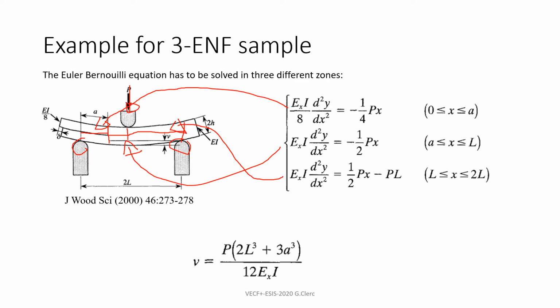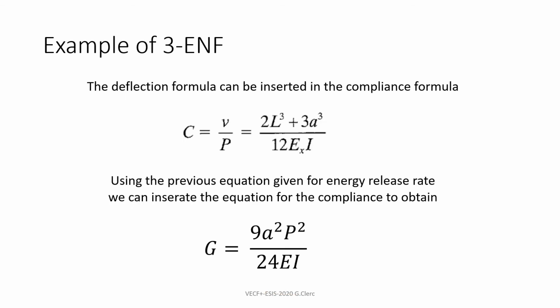If you want to see the detail, you can check this publication from Yoshida, where the solving is described in more detail. But here, due to short time, I will simply give you the solution. That's the deflection here in the middle of the beam. Then we know the deflection. With the deflection, we can use the formula for the compliance, which is simply the deflection divided by the load.